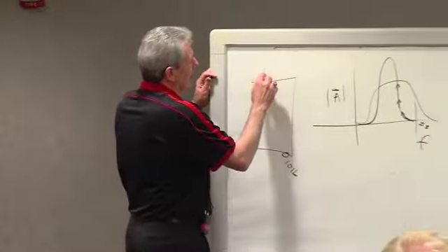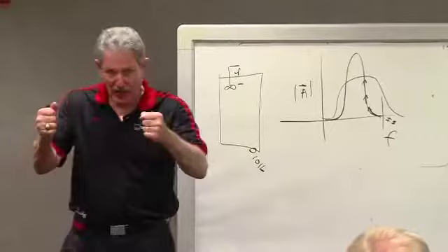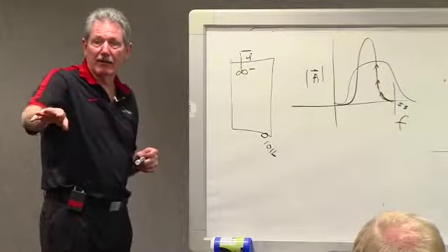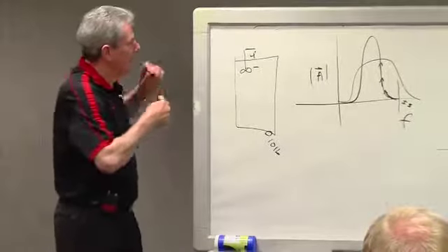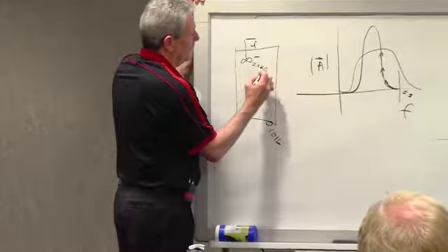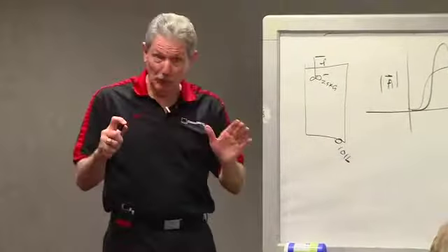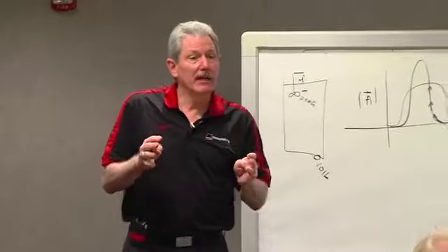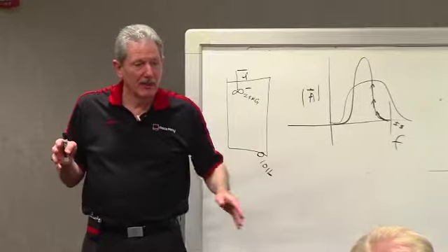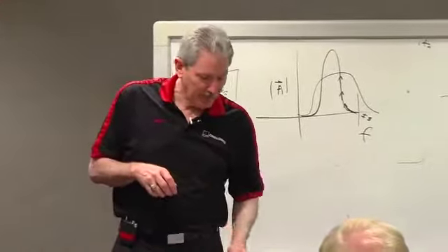Now you had this long steering column, and the driver would feel it like that. So, this is before the airbags, obviously, they put a 2.5 kilogram steering wheel damper. That was brute force, but it allowed them to sell the vehicles. It killed this problem, but it's such an inelegant solution.